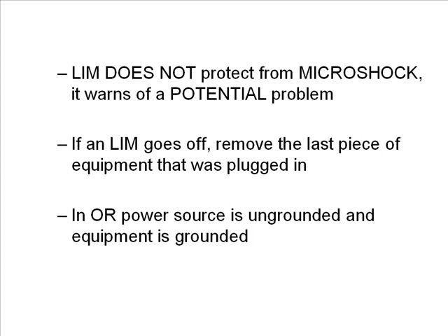Now, in some hospitals, the line isolation monitors are not owned by biomedical engineering. They're owned by physical plant. In other hospitals, they're the domain of biomedical engineering, and you've got to figure out which is which when you have a problem, because those two groups are separate and distinct. So, in the OR, the power source is ungrounded, and the equipment is grounded, and the line isolation monitor is used in this context. Rafi?